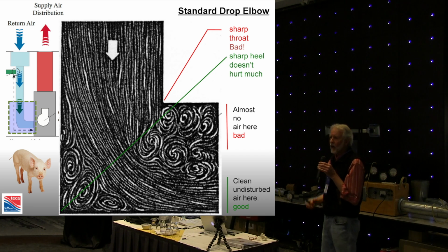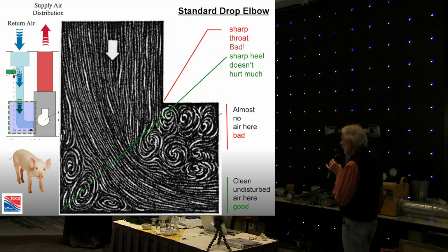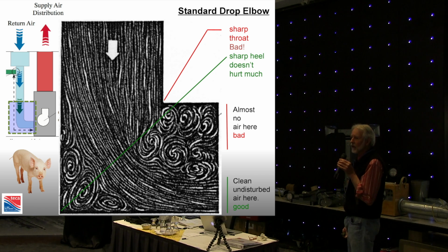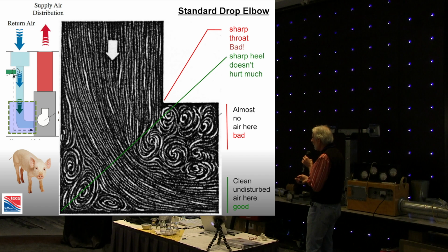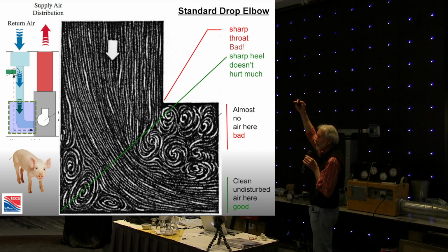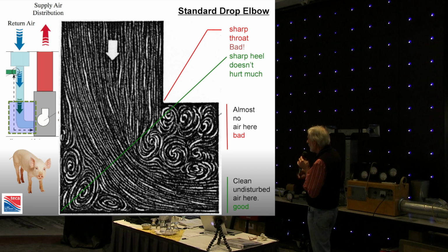At the time, they did not have the neat technology we have today, so this image was actually taken with a plexiglass duct and putting little wee soap bubbles into an airstream and using a strobe photograph. And what happens is, going back to the picture with Gary Milligan, as the air is coming down from the cold air returns in the floor above, it's nice and straight at this point because it's had 6 feet from the ceiling to straighten out and become what we call streamlined.